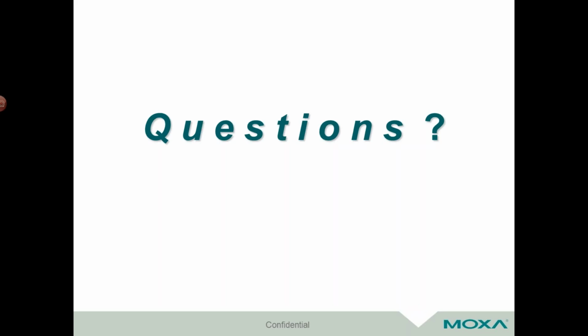All right, thanks, Oliver. Yeah, we do actually. Moxa has what we call our IW selector guide, and we can send you the link after this webinar, or when we send out the materials from the webinar today. Basically, it'll allow you to choose your device, what frequency you're using, what distance you're looking at, and then it'll help you select the appropriate antenna as well as accessories.